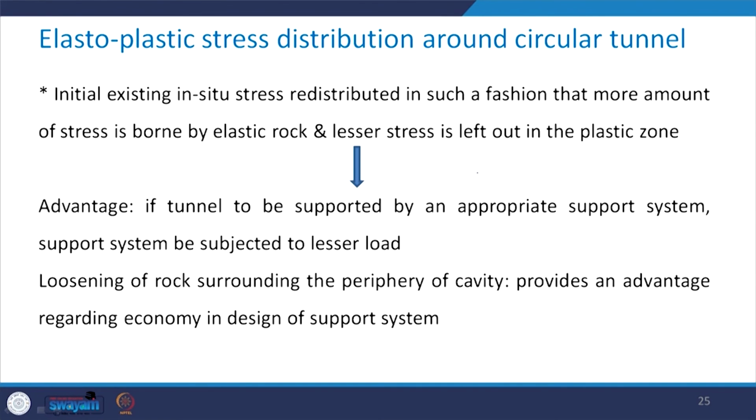The advantage of this is that if the tunnel is to be supported by an appropriate support system, that support system would be subjected to a lesser load. What happens? All around the periphery of the cavity in the surrounding rock, there occurs a loosening of the rock, and this provides an advantage as far as the economy in the design of the support system is concerned.